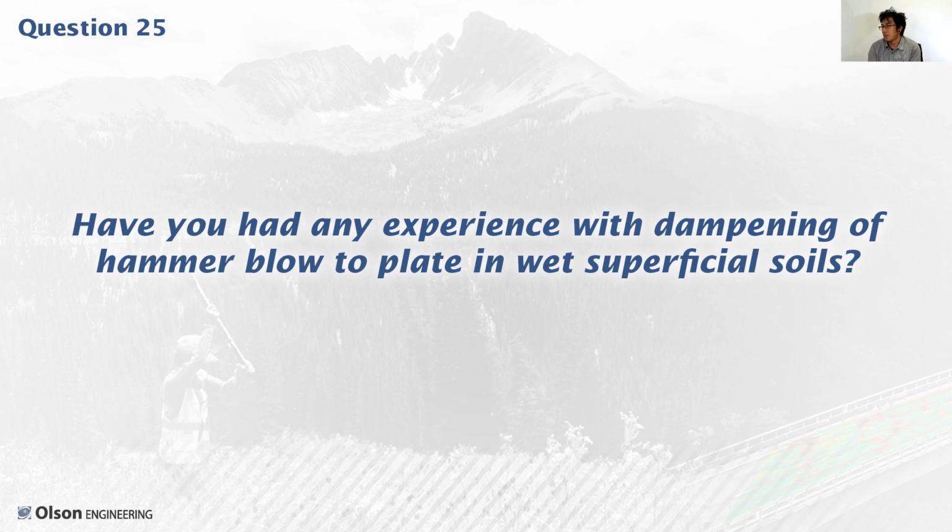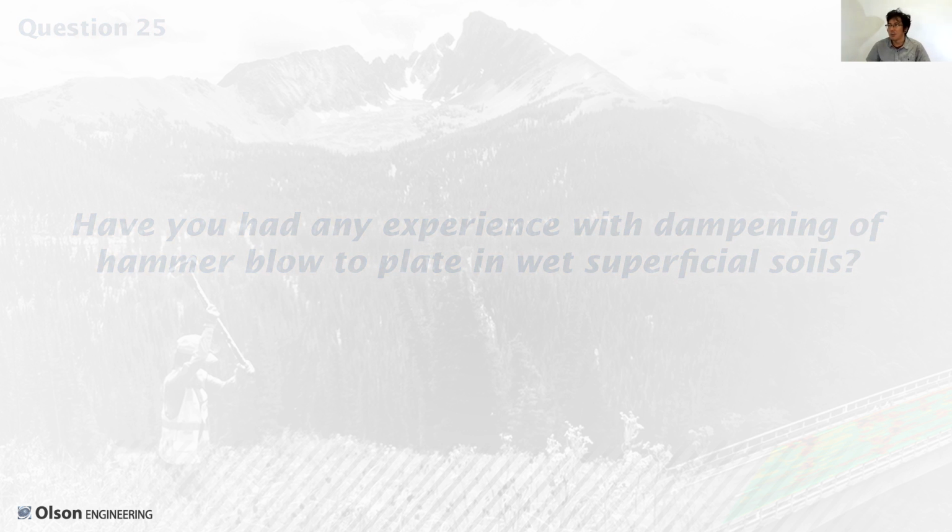Okay, next question. Have you had any experience with dampening of hammer blow to plate in wet superficial soils? Yeah, so we've had issues where our plate has sunk into the ground in overwatered lawns, super damp soils. And actually, once your plate sinks into the ground, and if it's stable and not sinking anymore, you get great coupling. So you actually get better energy input from your hammer strike. So I would say you're going to be fine as long as your soils are not super saturated. And as long as you're not losing your plate, I think you'll be fine.